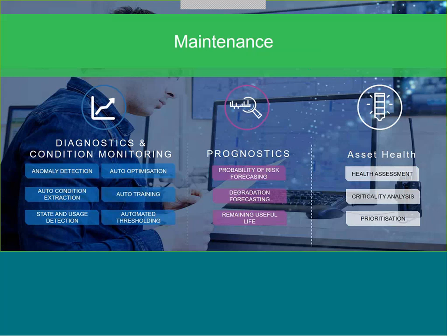But really, what we're referring to here in terms of maintenance is in a prognostic type of way. So this is with the devices that sit on your plant floor. So what we're really looking at is very clever ways of analysing probably different data from your systems. It might not be data that's coming straight from your PLC. You might have to add additional sensors to pull that out, because if you don't have things like temperature sensors or vibration sensors, it's very difficult for maintenance applications to be able to achieve that.